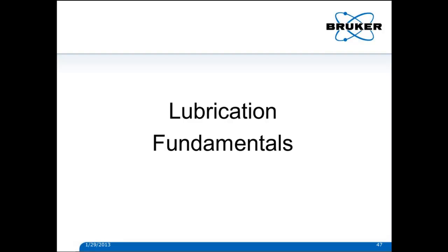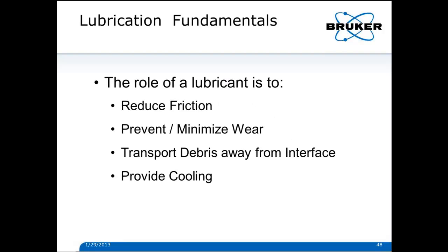Let's talk about lubrication for a few minutes. What is the function or the role of a lubricant? Well, there are four primary roles: to reduce friction, to prevent or minimize wear, to transport debris away from the interface. That's why many lubricant systems have filters on them. And to provide some coolant.